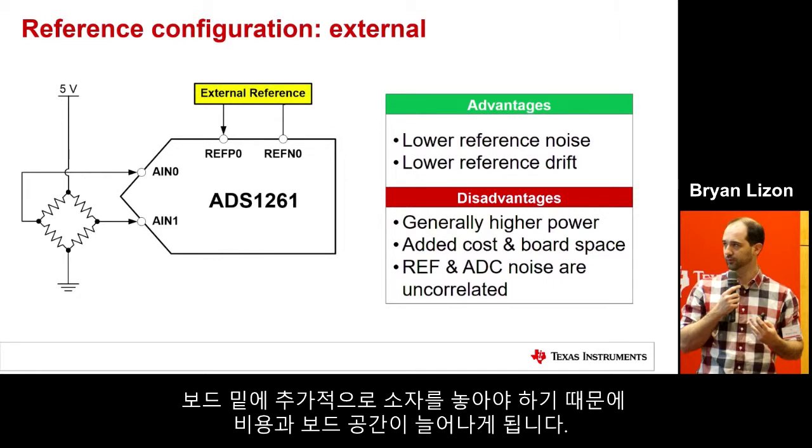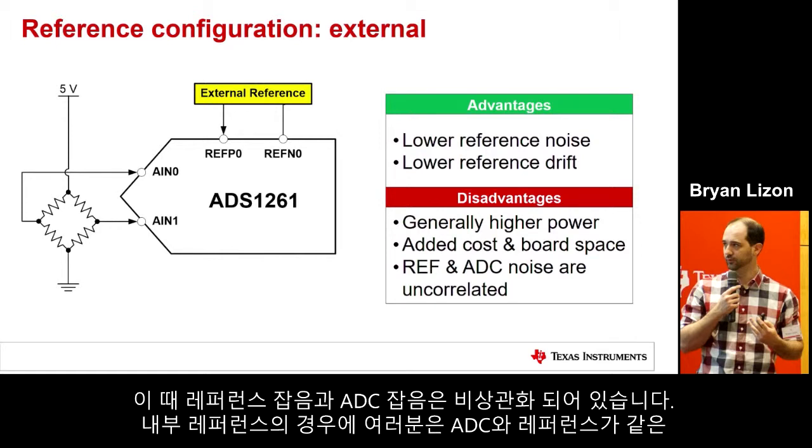It does add cost and board space. It's another component you have to place on your board. And the last thing is that the reference noise and the ADC noise are uncorrelated at this point.